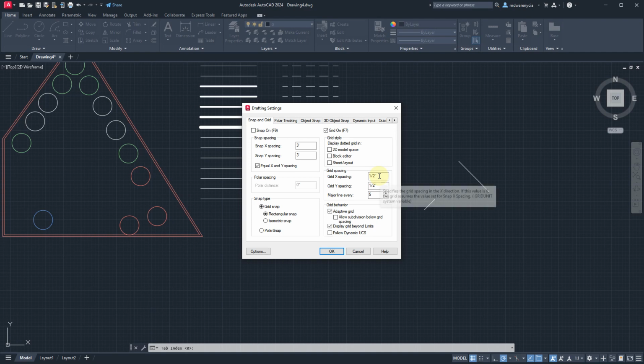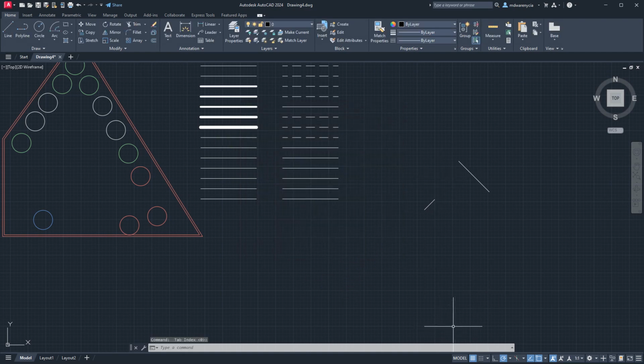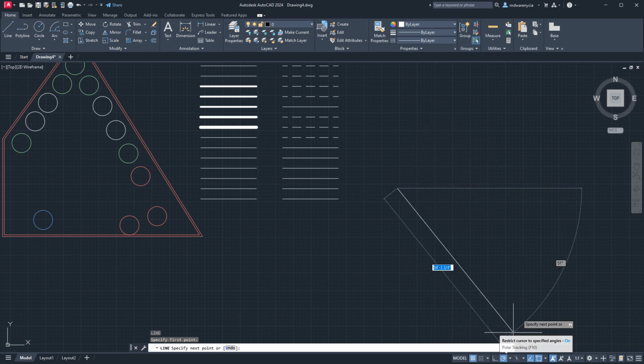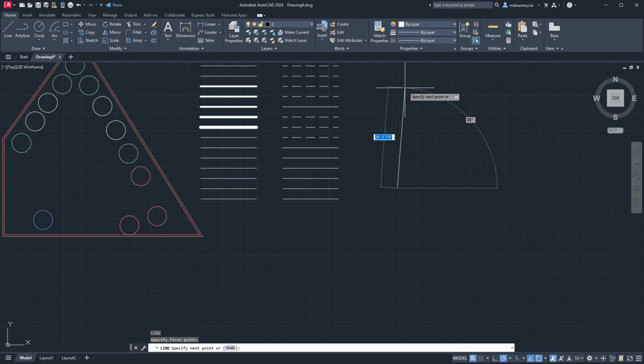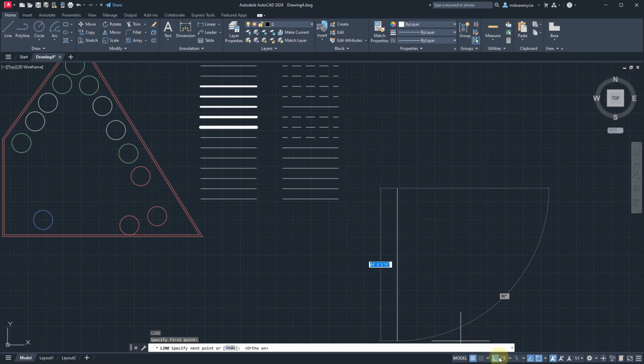You can also change your grid spacing if you wanted to, but yeah, I typically just leave the grid snap off. It's more annoying than anything else. It rarely does any good. This next option here is going to be the ortho mode, orthogonal drawing. It hard locks you in. So right now we did this setting with this one that lets you snap every couple degrees, every 45 degrees, I think. When you turn this one on, it's hard snapping you to a 90-degree angle right here.